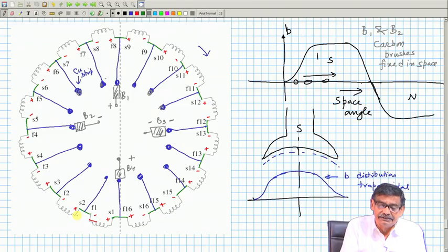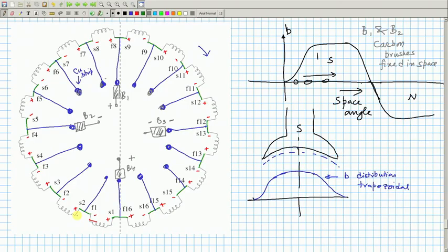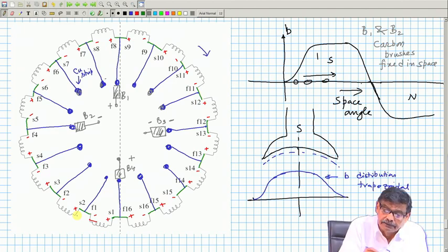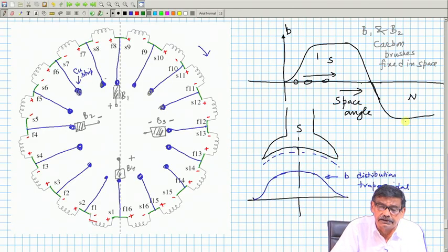So, have you got the idea? This is the essence of the thing. You have AC voltage fundamentally induced in each coil, no doubt, and it will be alternating in nature, because the B distribution is alternating, although not sinusoidally, it does not matter. It is trapezoidally varying. Therefore, I will get AC voltage induced across each coil. If you see the voltage waveform between these two terminals in the oscilloscope, it will be trapezoidal alternating. Only thing, this voltage and that voltage will have a phase displacement, because their positions are different in space.